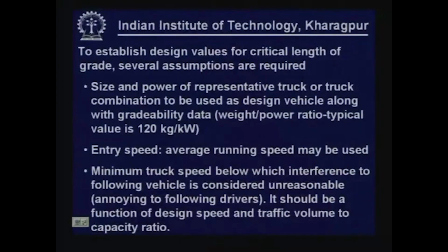Obviously, what is annoying will depend on the design speed for which the road is designed to accommodate. So, what is the minimum truck speed will depend on the design speed and also, logically, on the volume to capacity ratio.